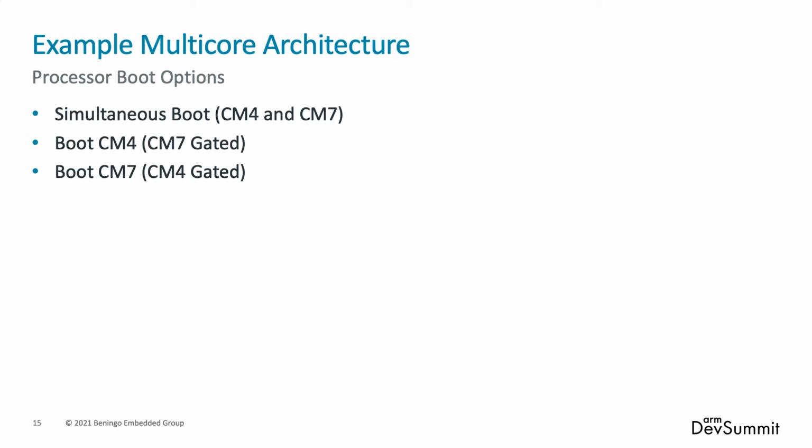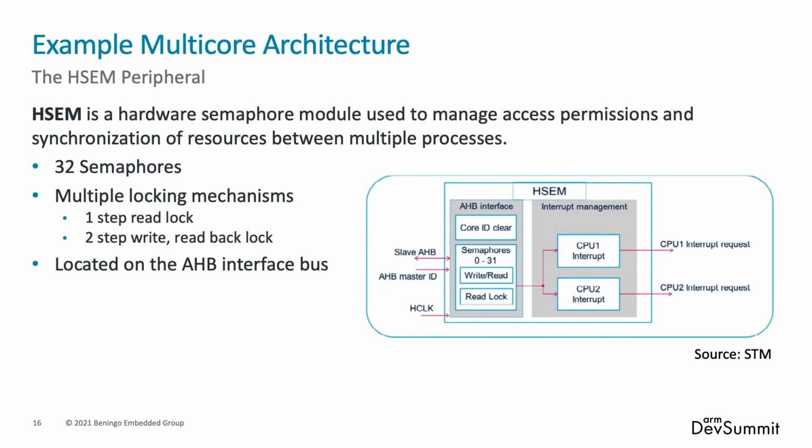So lots of different control there. Again, you just got to look at your application, see what makes the most sense for you. But suddenly there's lots of options here as we move into multi-processors on how that boot sequence looks. And each core can boot up kind of in the same way that you would normally find a single core processor to do. So it's not a completely brand new way of thinking for us. It's just there's a new way to start to coordinate behavior and a new level of control on how the application behaves in the hardware.